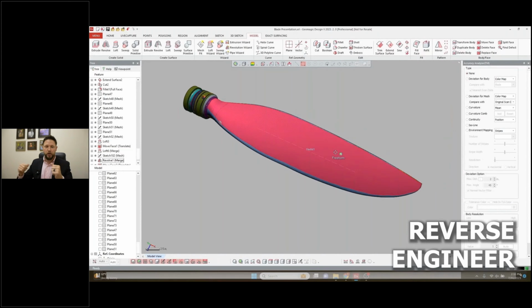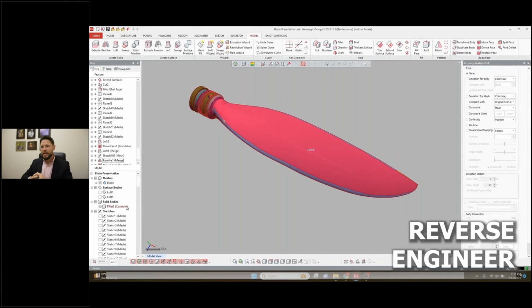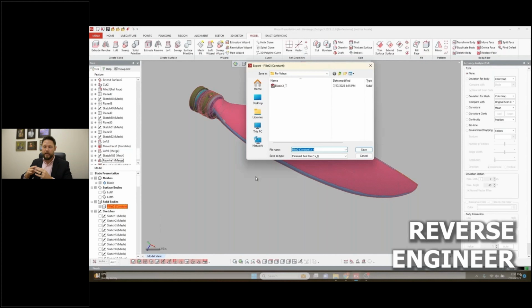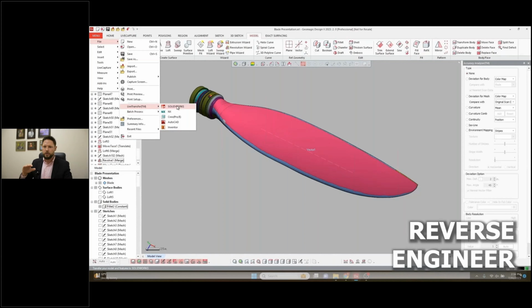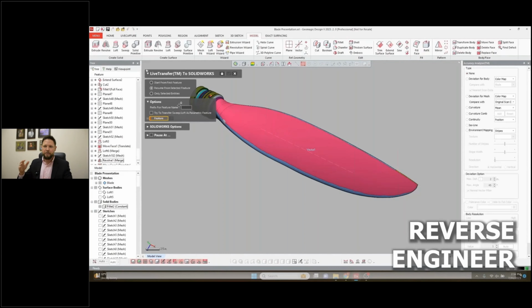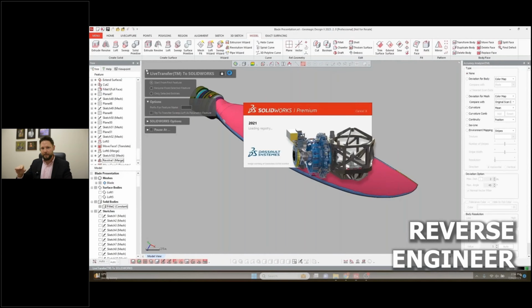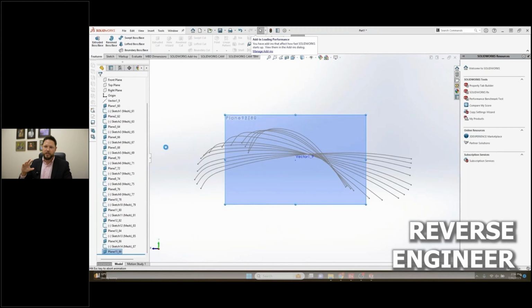Last step, double check your accuracy analyzer, make sure you're accurate everywhere on your mesh. And then from there, we can export that CAD file as just a basic solid with no history tree. Or what's really exciting is we can go to our favorite CAD package and transfer our tree line by line over to it and have our parametric feature there.